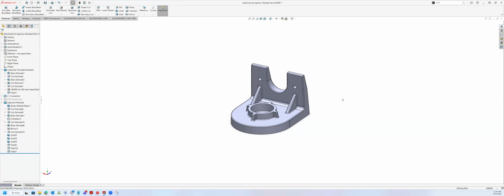But that is a great point, because there are some things that can be done to reduce material and keep the same strength that you're looking at. So that is great. Yeah, I was just concerned with that 12 millimeters thickness. You wouldn't mold that. You'd have sinks all over the place. Probably warpage.